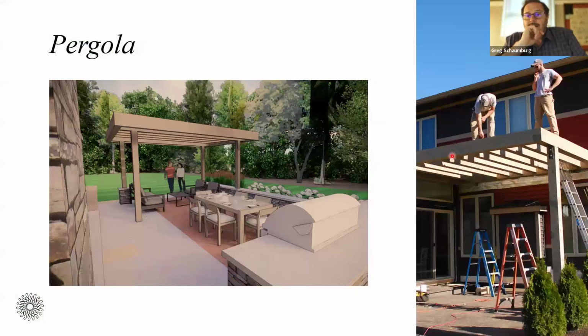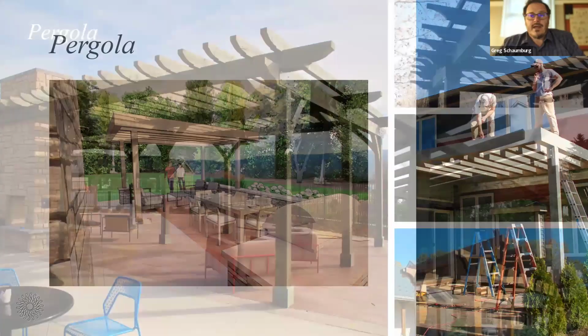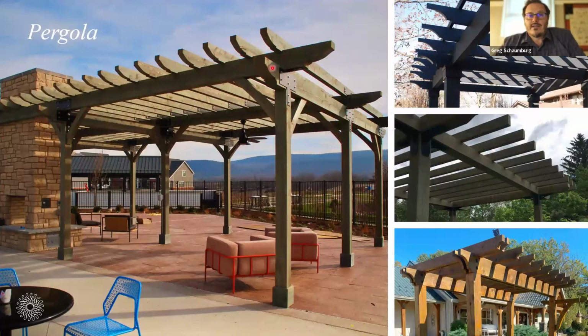And then from a pergola example, you'll see, oftentimes people think about pergolas as just being, they have to be a certain way, right? With decorative end cuts, and they have to be built a certain way. This was a little bit more modern feeling to it. This one was built with a house that was a little bit more streamlined, and this was conceptually a similar idea for it. But, to control the force of racking, all we had was a 90-degree custom steel bracket that was real tall. That was really minimalistic. It worked with the aesthetic of the home. So you don't necessarily have to be tied into something as traditional looking as this. Even this is a traditional pergola structure.